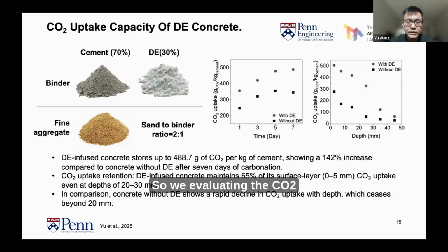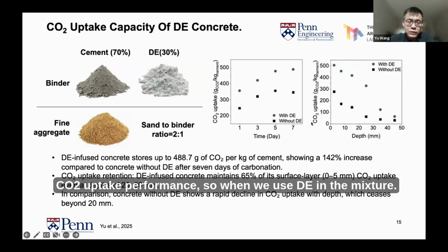So we evaluated the CO2 uptake capacity of this mixture, and we can see it at 1 day, 3 days, 5 days, 7 days. First, no matter with DE or without DE, we can see an increased CO2 uptake capacity with longer curing days. However, as we add DE, we can see a higher CO2 uptake capacity compared to the mixture without DE. So it shows better CO2 uptake performance when we use DE in the mixture.